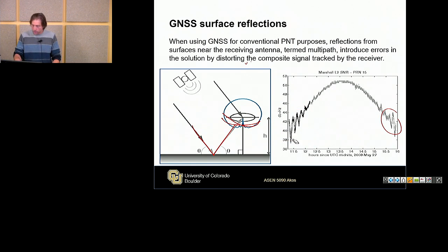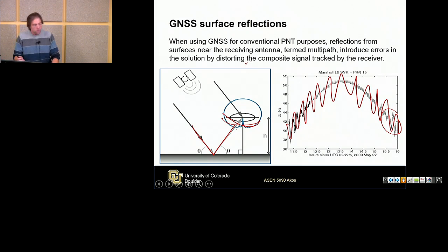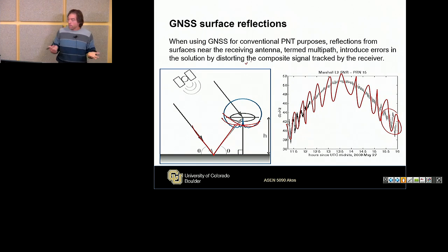And if I look at what that looks like, I get these huge oscillations all the way over the path of the satellite, because I'm getting that reflection from the ground as well as the direct signal. Now my antenna went from being $2,000 to about 20 cents. And I don't have to use a $6,000 receiver anymore. I can use a mass market receiver, which is in this guy, to give the same conditions. So I can build a very effective snow sensor for tens of dollars.